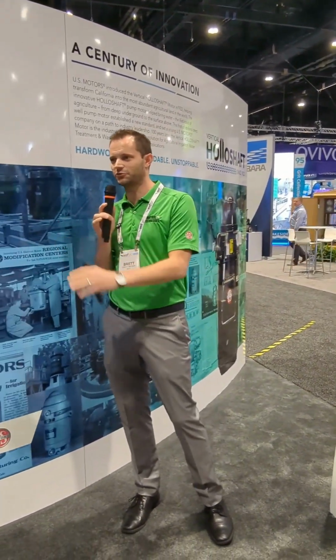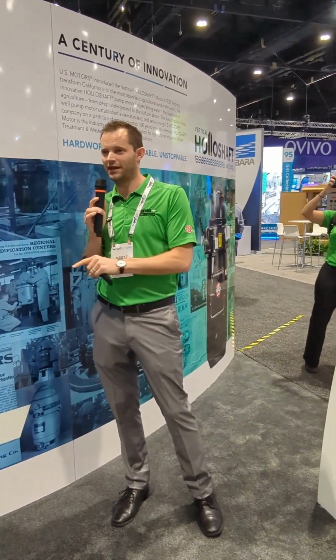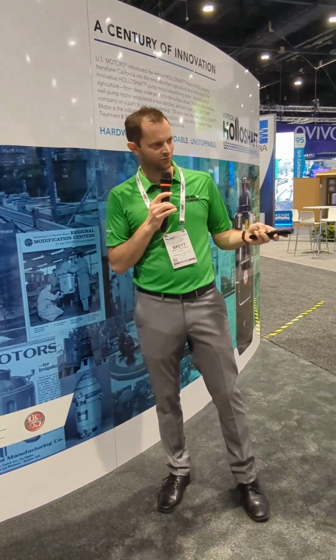The second way we do this is with HMIs. Now HMI is your touchscreen interface, your phone's technically an HMI. What we can do is have embedded web pages. So you actually pop in the IP address of that HMI, and you've got an embedded web page. You can access the HMI from anywhere in the world. So if you want to just control the drive or see what's happening, this is the way to go.